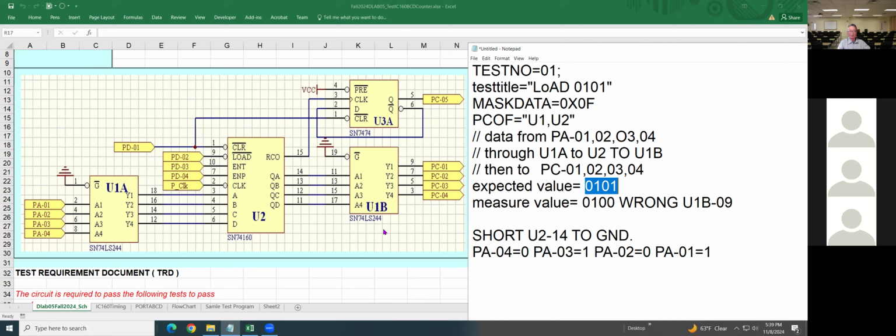What can you answer? You say, okay, I measure pin 9, logic 0, however, pin 11, logic 1. I said that's not enough information. To get pin 9 equal pin 11, pin 19 must be ground. So the answer will be, I take pin 11, I get logic 1. Pin 9 not. Then I take pin 19 ground. That's why I want to change U1.